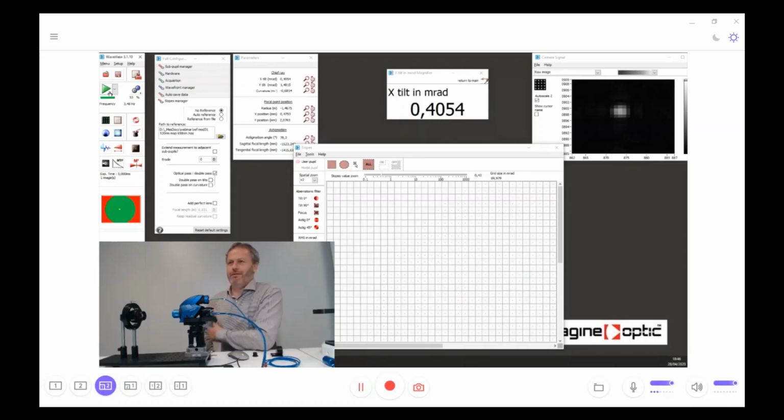Yes, of course, as for all optics, temperature affects the aberrations, probably the focus term firstly. Our advice, of course, is to always have in hand this kind of concave mirror I described in order to redo the calibration from time to time.